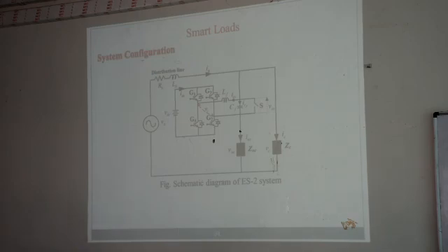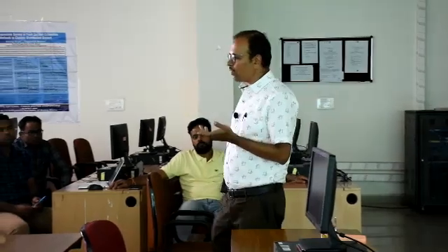Another big concept is coming, which is a smart load, which is taking care of a big part in demand response management. In the very beginning I told you that now the time is coming where your load should also be smart. Right now what is our load? It is not smart. If it says I need 100 watts of power, then you have to give 100 watts. You will sacrifice a little bit if your grid is not supporting. The voltage will fall, and if it is a static load, then naturally the demand will also rise. But this situation is not good for your grid stability.